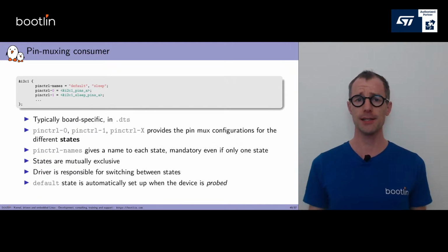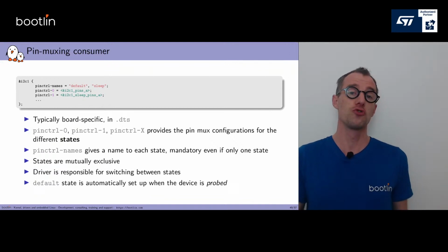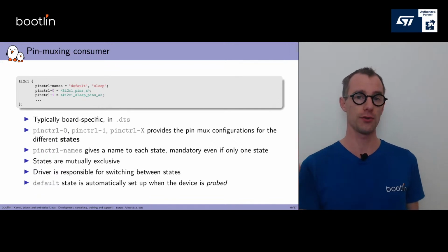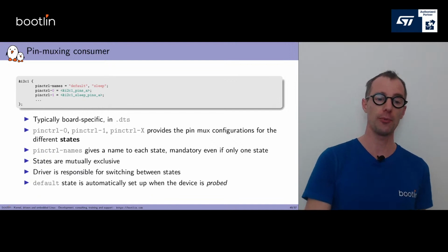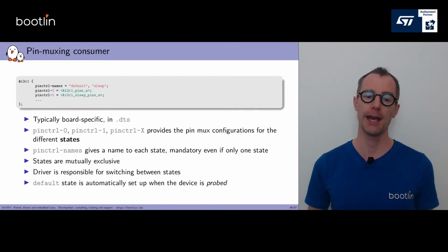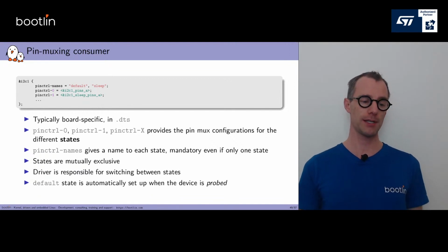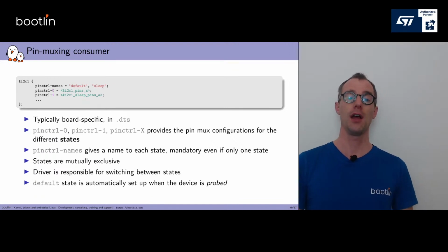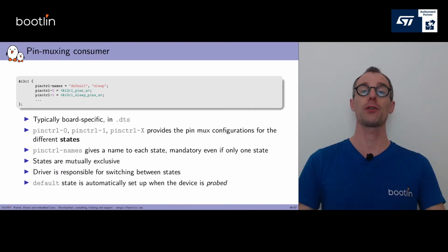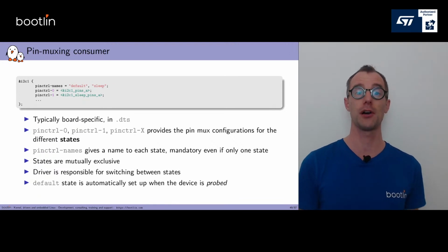In most cases, you usually only have a single state called default with a single property pin control 0, and a state called default is automatically set up and configured when you boot the system and when the driver is initialized for that particular device.